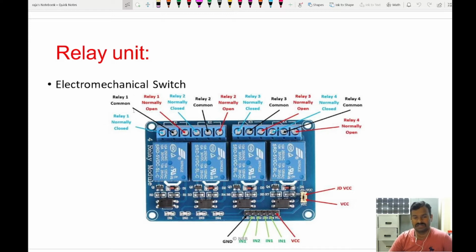this sort of abnormal conditions. Because you are getting all the data, you can just add a condition: in case of overload, or in case of over voltage, turn off this particular load, or in case of peak load time, turn off this. Any sort of logic can be written. So for that purpose, this relay can be used.